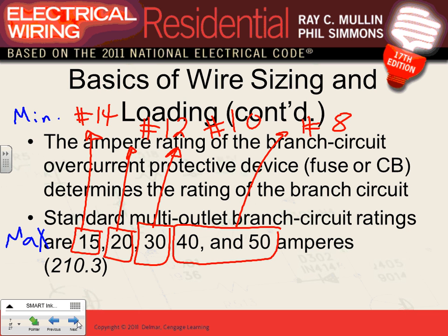So can I put number 8 on a 15 amp? Absolutely. Where would you do a situation like this? Can anybody give me an example? Voltage drop. Voltage drop, thank you. Long runs. Absolutely. A long run, a parking lot. Parking lots, voltage drop, typically outside circuits. That's when we use a bigger conductor on a 15 or 20 amp circuit. So these are your circuits.